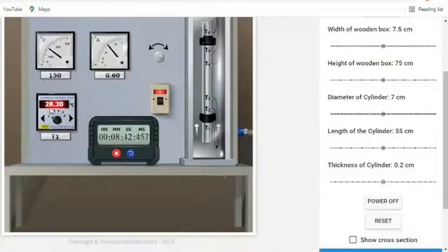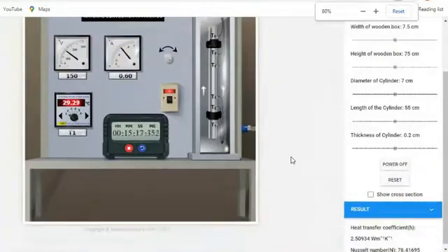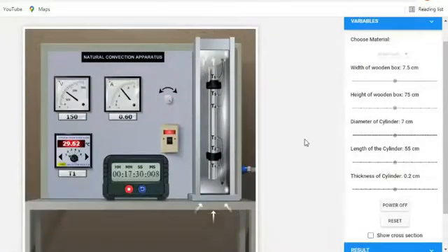Don't take a reading because you see here, up to 20 minutes is required for a steady state. Once the steady state comes, then we can take a reading. Now you see there is a continuous fluctuation, and after the 20 minutes this gets stopped, and you can check the temperatures. All are set, meaning the steady state has occurred. And on the steady state, we use the equations to calculate. That's why it is very important to get a steady state. Okay. Now, once this clock shows 20, it means everything is correct.